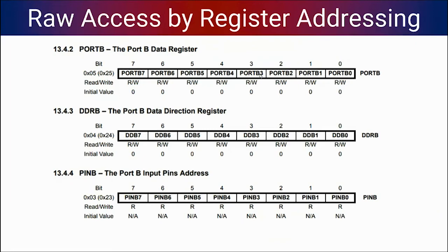So now we have covered this, where we were directly using this macro sort of thing, mentioning PORTB is equal to 32, or using this DDRB, the names of the register is equal to 32. This was either 32 or 0, right? We can also use the address. Instead of using the name, you can directly use the address, and if you do that, it will give you more confidence. Just by using the address, you can directly manipulate those registers, right?